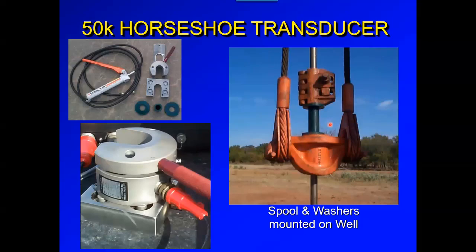This spool piece and spool spacers are relatively cheap and easy to install. From a personal perspective, whenever I utilized Echometer equipment in the field that I was managing, I put it as a normal tool on each one of the artificial lift installations that we did for rod pump, so that they all would possess the spool spacers and the spool piece. That way we could easily and efficiently take 50K load cell measurements throughout the field without having to stack out the wells. A little bit of tying reality with the PowerPoint presentation: this is something that we utilize on a daily basis, I would say.